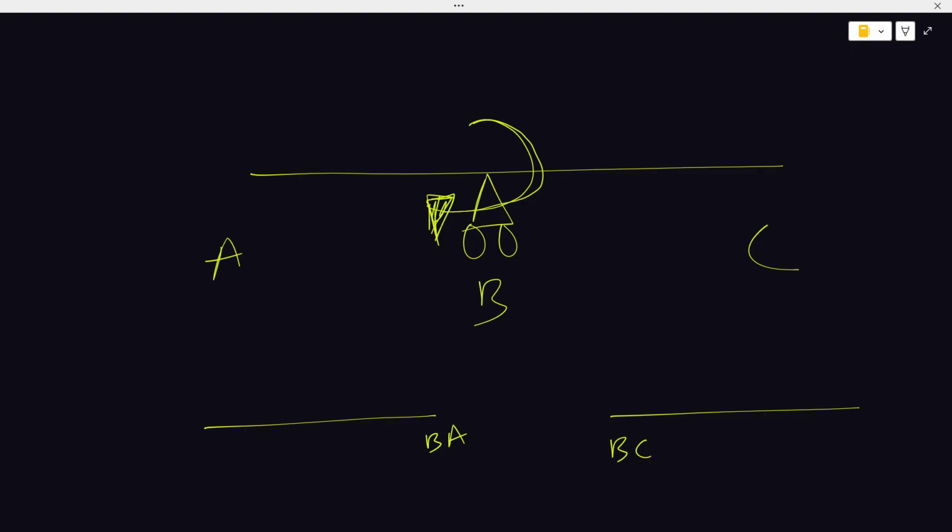So I won't just say that if this is M, let's say M over 3 goes here, and the remaining one, 2M over 3, goes there. I can't just say that, since we're dealing with member end moments, from the transfer of joints to member ends.